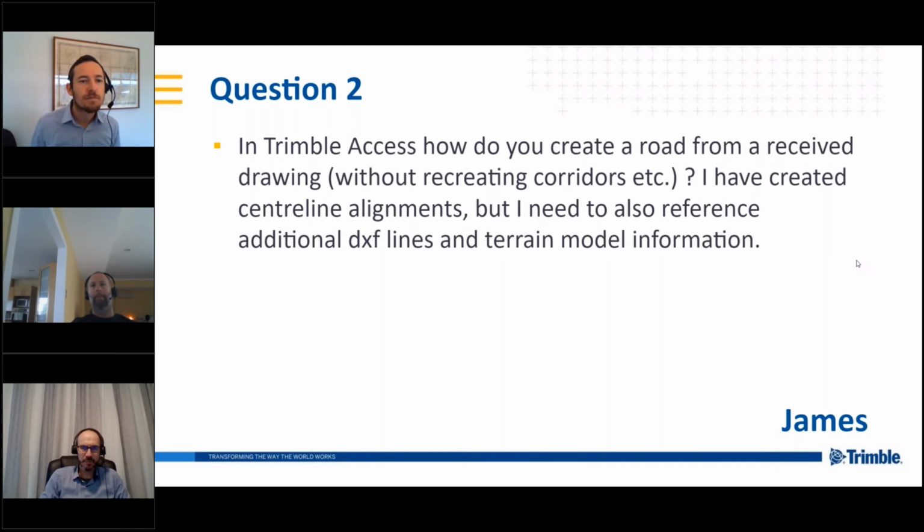So, yep, they've got the alignment from a polyline, and they're now wanting to assign other DXF lines to it. Now, with a DXF file or any sort of background file that contains polylines, you can create the master alignment from that just simply by selecting it. However, you cannot assign sub-alignments to it. So if you want to create a full road design within Trimble Access roads, what you'd need to do is create some templates and assign that to your master alignment.